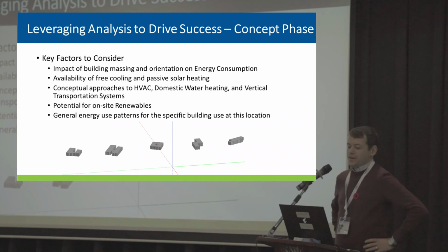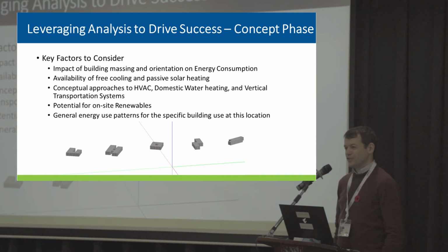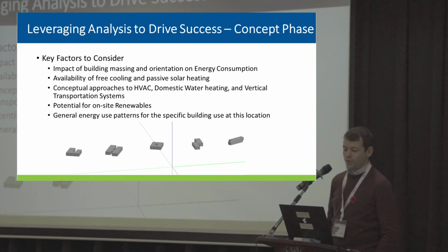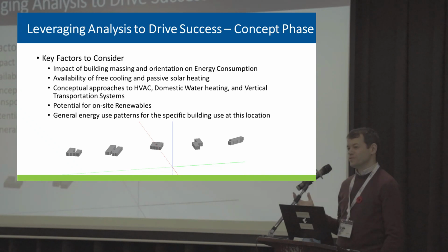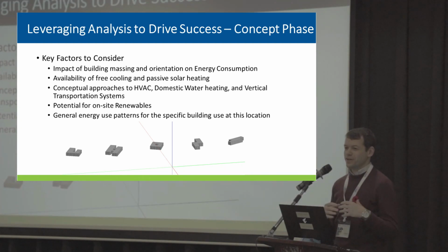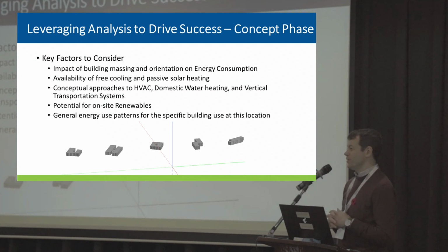So as I mentioned, there's no prescriptive path for this guide, so they want you to perform analysis. They have a whole chapter on leveraging analysis to drive design. So for example, in the concept phase, usually your building form isn't chosen, so you might start out at the concept phase looking at different masses of buildings. It may be, do you want your building to be 2 stories, 3 stories, 4 stories? Do you want it to be orientated on an east-west axis? You can look at all these different forms and then see how that impacts your ability to install renewable energy to make your building zero energy.